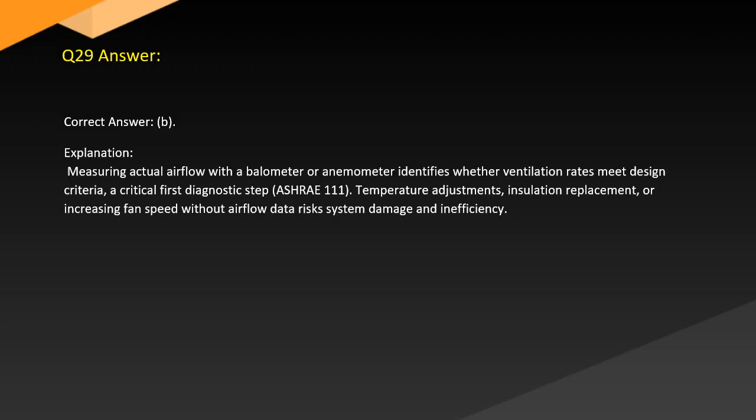Answer. Correct answer, B. Explanation. Measuring actual airflow with a balometer or an anemometer identifies whether ventilation rates meet design criteria. A critical first diagnostic step. ASHRAE 111. Temperature adjustments, insulation replacement, or increasing fan speed without airflow data risk system damage and inefficiency.